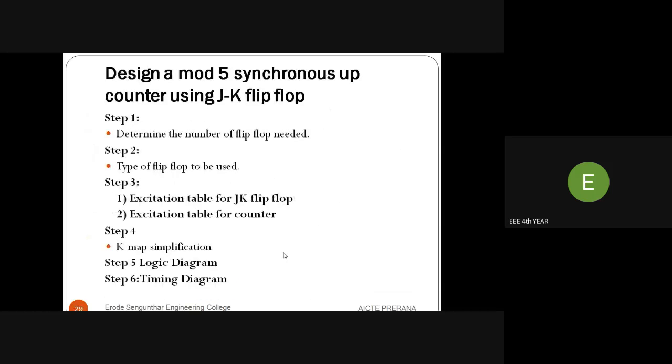In this modulus counter topic, we are designing a modulus synchronous up counter using JK flip-flops. To design it, we need to follow five steps. Step 1: determine the number of flip-flops needed. Step 2: determine the type of flip-flop to be used. What type of flip-flop can we use? The first step is to determine the number of flip-flops, and the second step is to find the type of flip-flop.